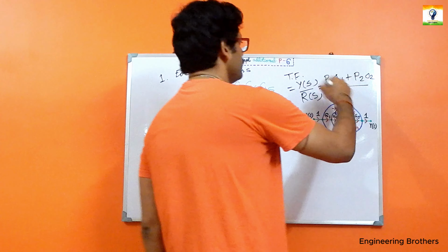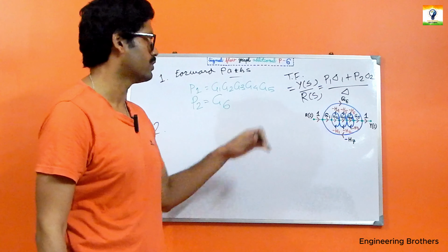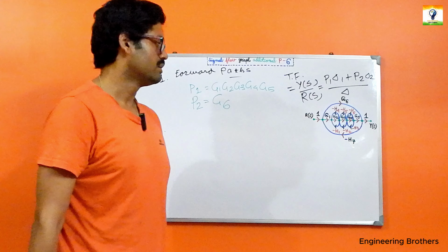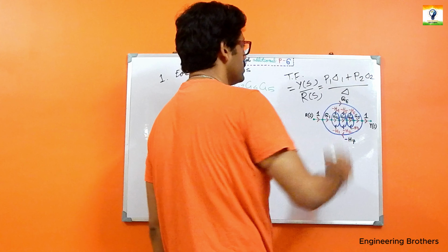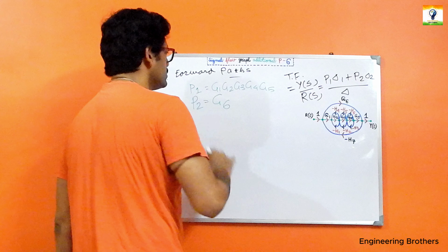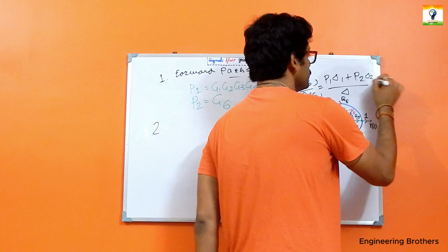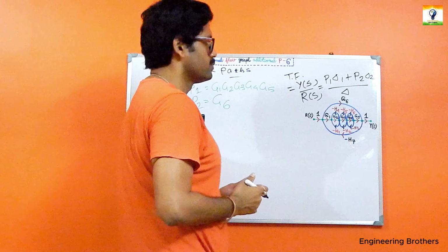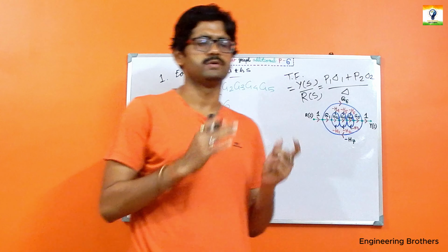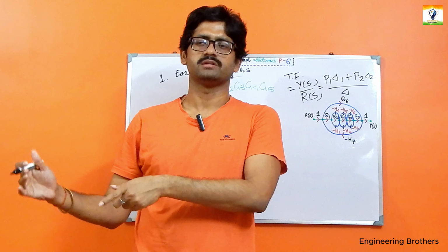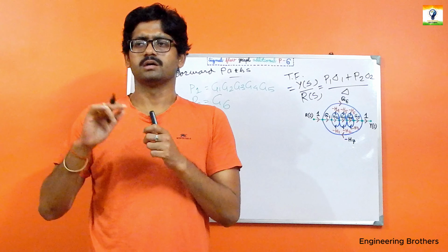To find delta, we should consider the individual loops. This is the formulation for our transfer function, applying the Mason gain formula. As we have 2 forward paths, the formulation stops right here. If there are more forward paths, the numerator would continue as P1 delta 1 plus P2 delta 2 plus P3 delta 3, then P4 delta 4 for a fourth path, and it goes on like that.